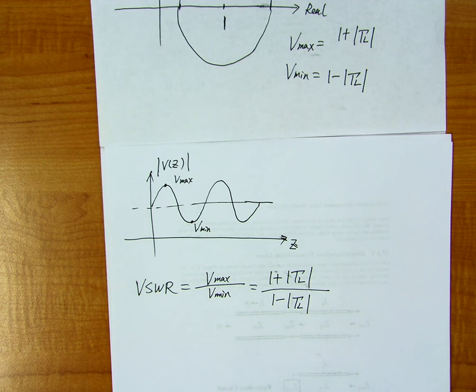The reason we define this quantity is that it's not very easy for engineers to measure the voltage in a microwave system, because as the frequency increases, the voltage between 2 points is not uniquely defined. Because you have varying magnetic field, if you measure the integral of the electric field along different paths, although the starting point and ending point are the same, the path is different, so you have different voltage. So the voltage is not unique anymore.